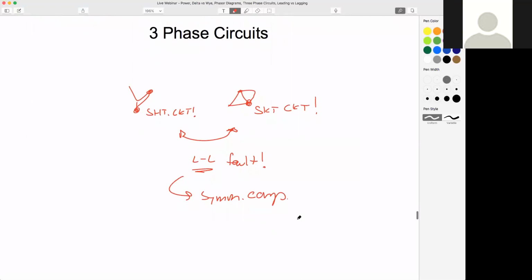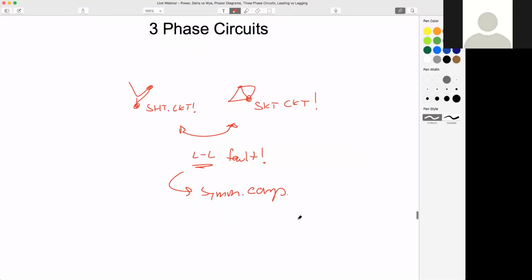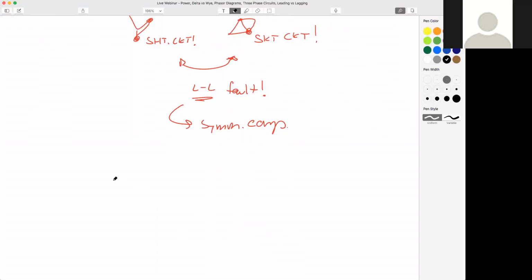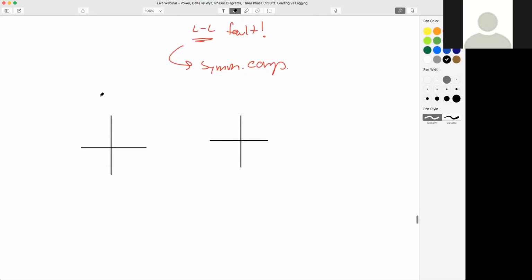Mary said, for a negative sequence, is our line voltage still leading? Okay, I'll talk about that really quick. So let's draw 2 phasor diagrams. And to save time, I won't draw every single individual line and phase. I'll just do the A line and A phase. So everyone knows ABC is the same thing as positive, and ACB is negative. Sometimes it's ACB, sometimes it's BAC, right?